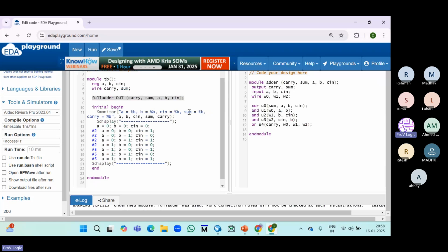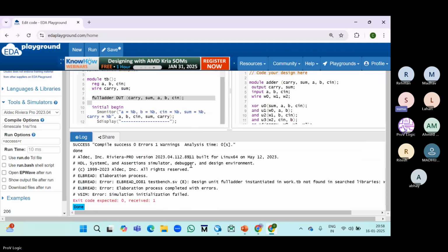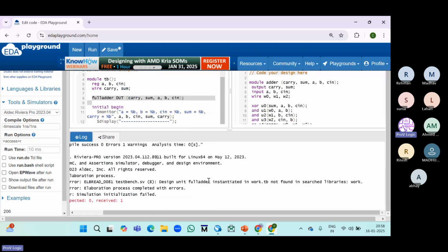Just one line. In Verilog HDL we just write in one line, but in SystemVerilog it is a very complex thing. Okay, so this is how we connect, simply in one line. Yeah, DUT is compulsory. If you don't mention the DUT, it doesn't connect the design with the test bench. Interfacing doesn't happen.